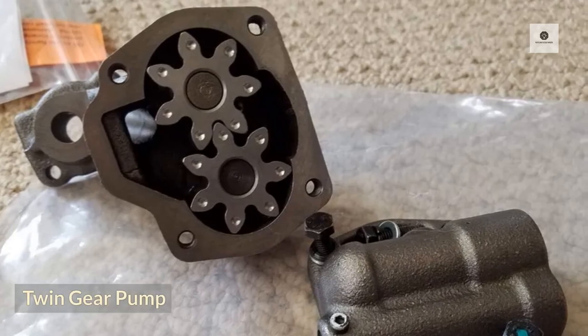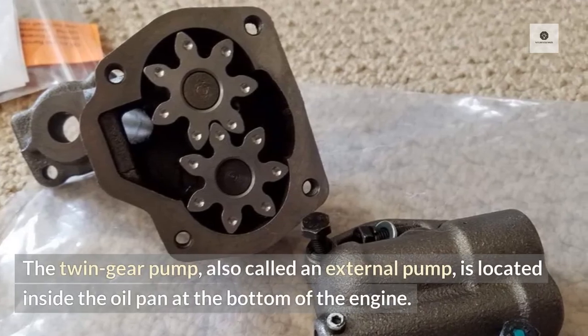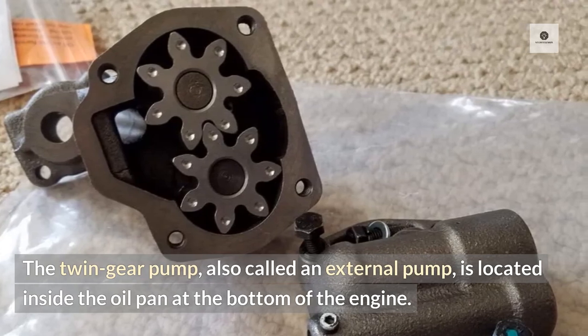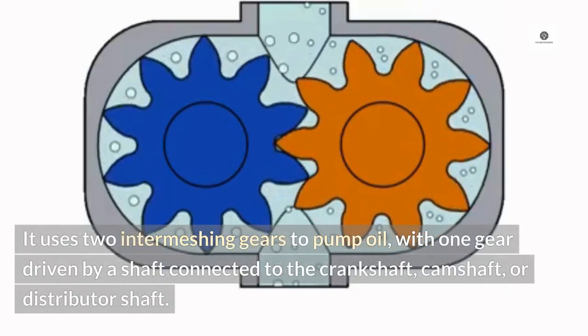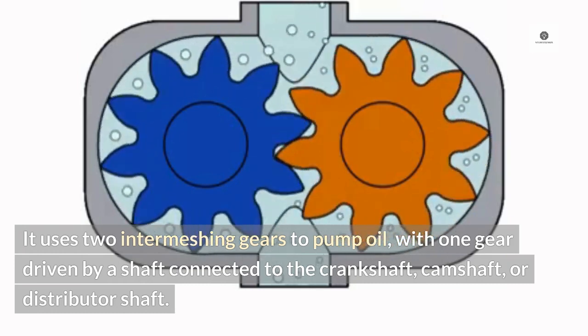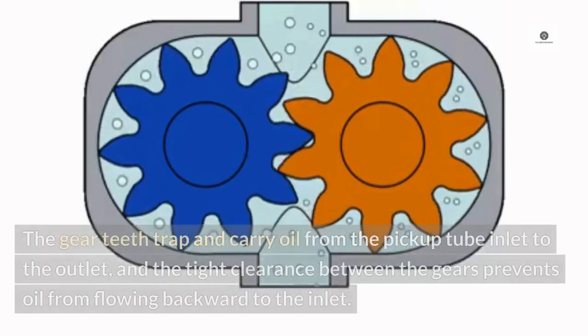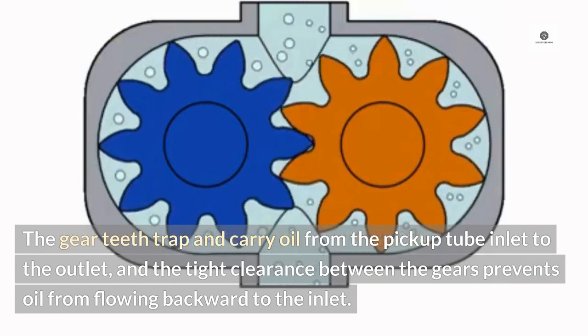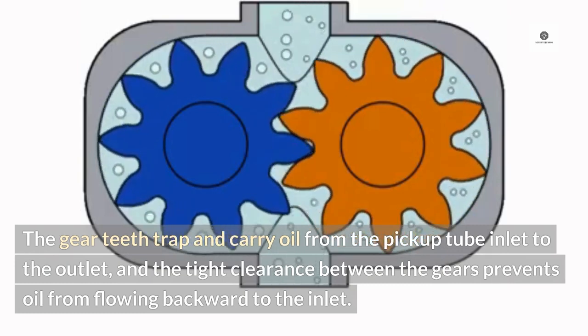Twin gear pump. The twin gear pump, also called an external pump, is located inside the oil pan at the bottom of the engine. It uses two intermeshing gears to pump oil, with one gear driven by a shaft connected to the crankshaft, camshaft, or distributor shaft. The gear teeth trap and carry oil from the pickup tube inlet to the outlet, and the tight clearance between the gears prevents oil from flowing backward to the inlet.